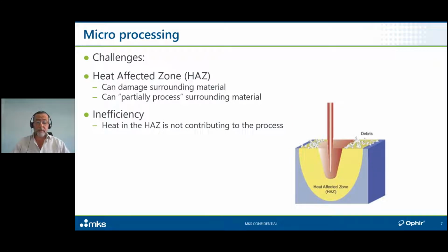Okay, so we have an application requiring a delicate touch. Now, let's remember, inside that space within which the power density is high enough, I'm vaporizing or cutting or otherwise zapping the material. Outside this space where the process is happening, I might not be vaporizing the material, but I'm certainly affecting it due to the heat. During the course of the pulse, certainly in a continuous beam, but even if it's a pulsed beam, the heat spreads. Here we see what's known as the heat affected zone.